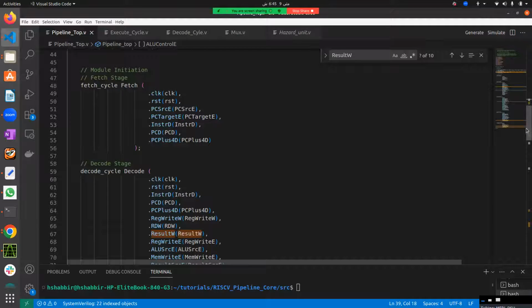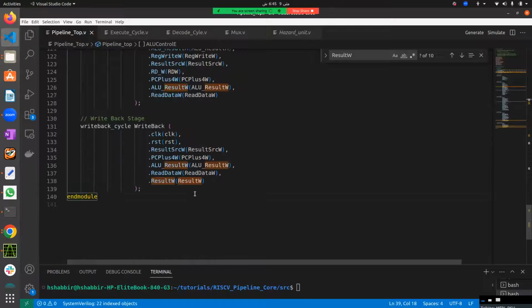I'm not putting the hazard unit into the execution unit, definitely, because if you enhance your implementation or architecture, the more hazards you are going to face. So those logics can be implemented in the hazard unit. That's why I'm instantiating it in the top file rather than in some of the internal stages, right? So let's quickly instantiate our new module here.